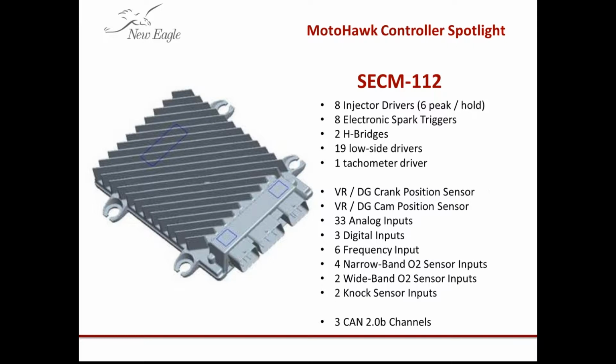So talking about the I/O here, we've got 8 injector drivers, 6 of which can do peak and hold, 8 ESTs as well, electronic spark triggers. You've got 2 H bridges for driving 2 different throttles if you've got EGR or something in your system, 19 low side drivers and a tach.